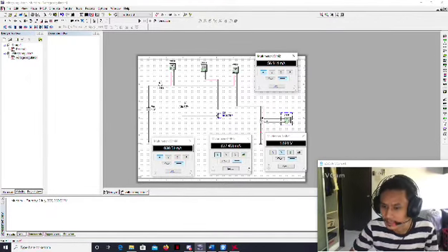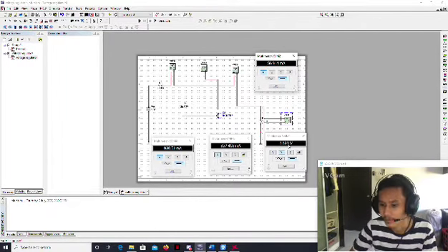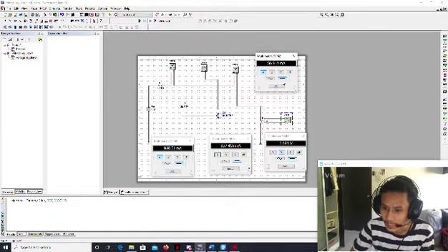The first multimeter shows VL. The value that I get is 5.691 volt. The second multimeter is for IL, and the value that I get is 56.914 milliampere.